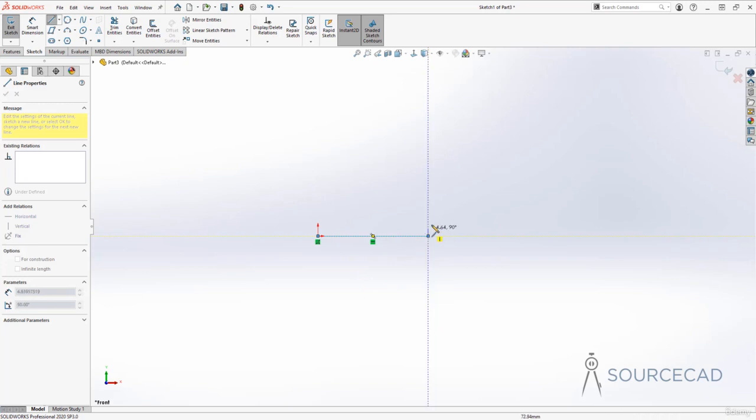Now I've started the line. I'll click on another point here. Now here what I see is length, so I'll just click again, then again randomly. But before I do that, just look at all these yellow dotted lines. Now these yellow dotted lines are the reference lines, and they will help you make your drawing precisely. So in this case, if you want to make a line which is perpendicular to your existing line, then simply move over this yellow dotted line, and now it's perpendicular, and when it is, it will show you once again that perpendicular constraint or the perpendicular relation.